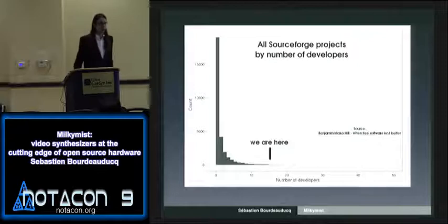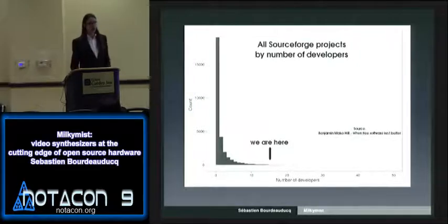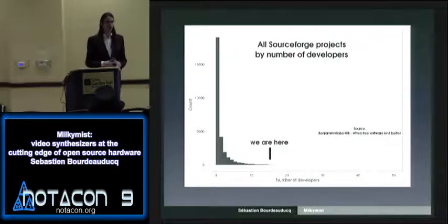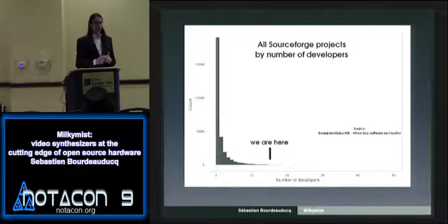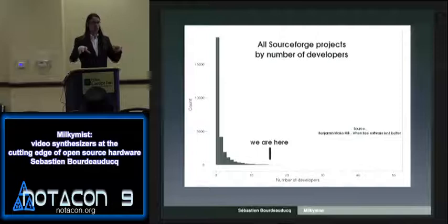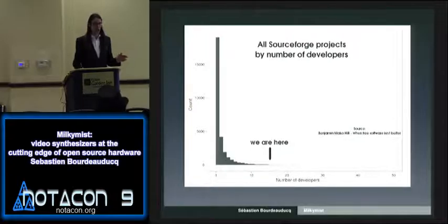I'm going to talk about this very briefly later, but I am in the process of completely refactoring the system on chip, and it will be possible to run the DDR at a multiple of the system clock frequency with the next version of the system on chip. The memory controller will be able to reorder transactions and also issue several commands to the DDR in one single clock cycle by just running multiple state machines in parallel, each taking care of one of the DRAM banks. I don't know if it makes sense to you. Do you know about DRAM or?